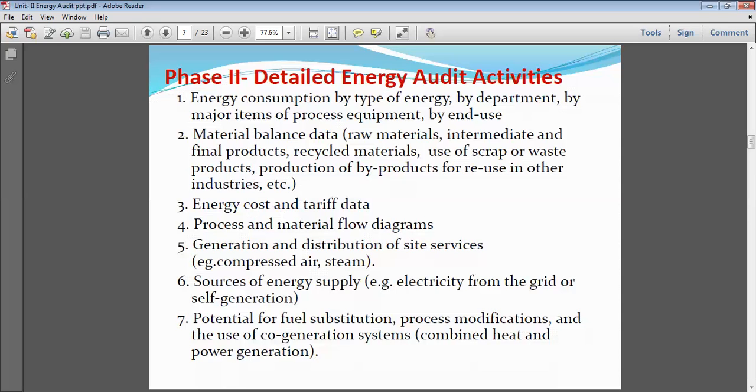And if you examine all these parameters, you come to know that our maximum demand is very small, whereas our contract demand is very high, and hence we have to pay more money. Or our contract demand is smaller, whereas we are drawing more than our contract demand, then you have to pay the excess demand charges as well as a penalty.